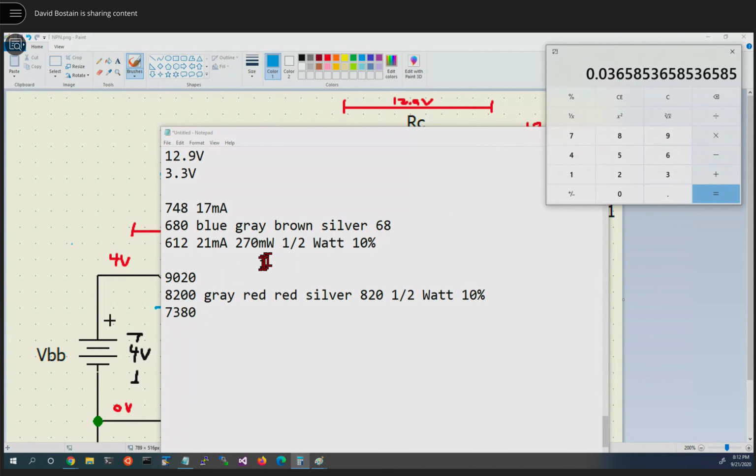So you should be able to do that, I guess. That would be a reasonable thing for you to do, is to check. And the wattage, of course, could be checked here as well. If we took our biggest number and divided it into 3.3, divided by 7380, it's going to equal that, which we take and multiply back. We've got two things we could do here. One is times 3.3, which is going to say, okay, that's a very small number, so the wattage on that could have been 1/8 of a watt. However, since we bought 1/2, we'll buy another 1/2 over here.